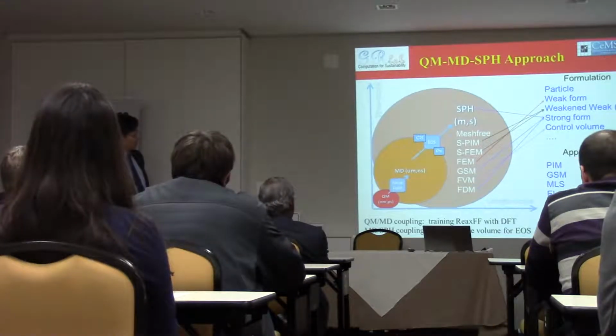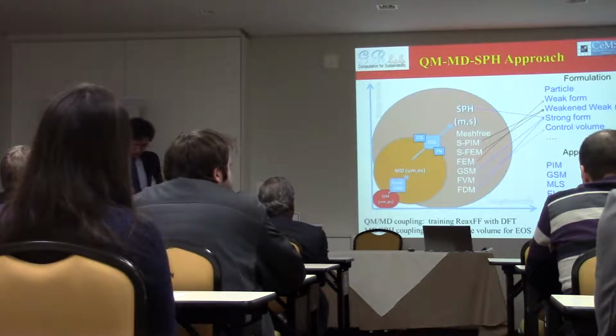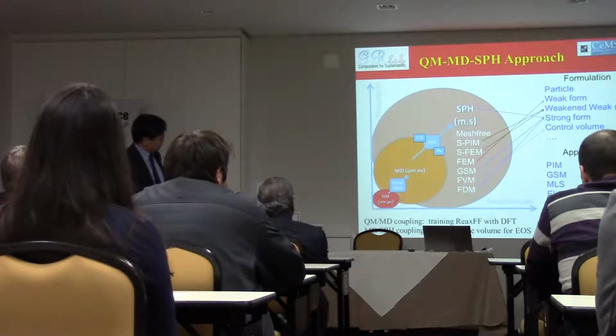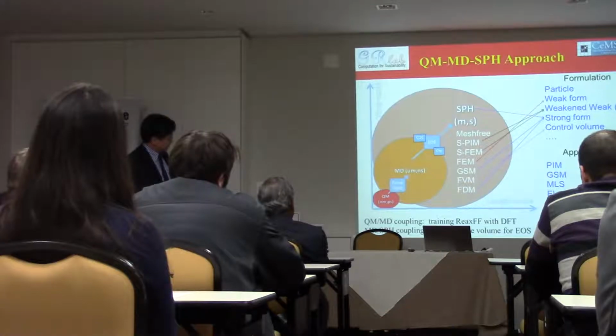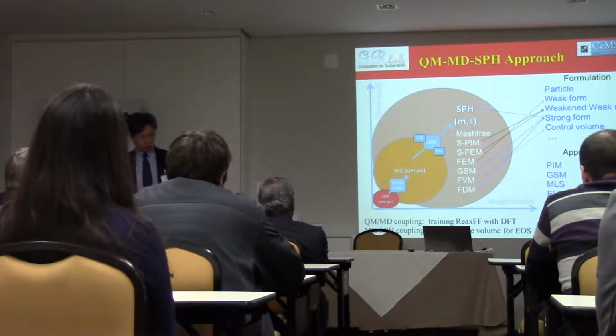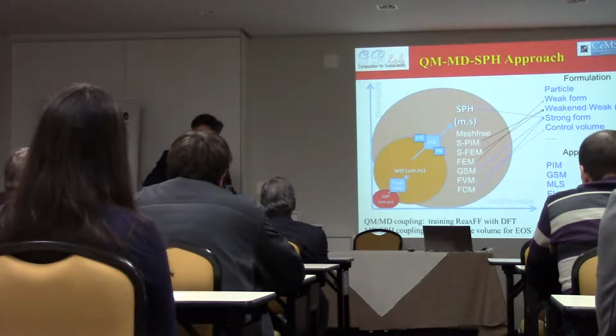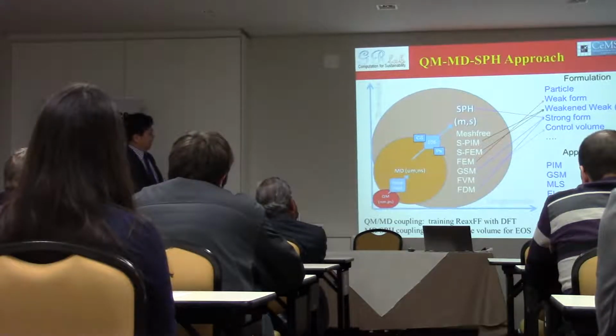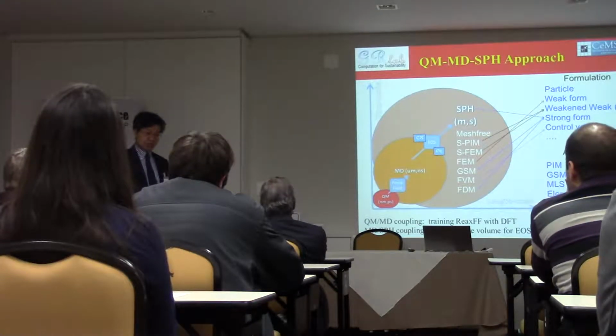But what you need to do is called approximation. If we're talking about approximation based on elements, which is FEM, then we know how to do it. We basically look at the element with nodes, we do simple interpolation, and we get the approximation done. But in the mesh-free community, there are all different types of other ways to approximate the function.